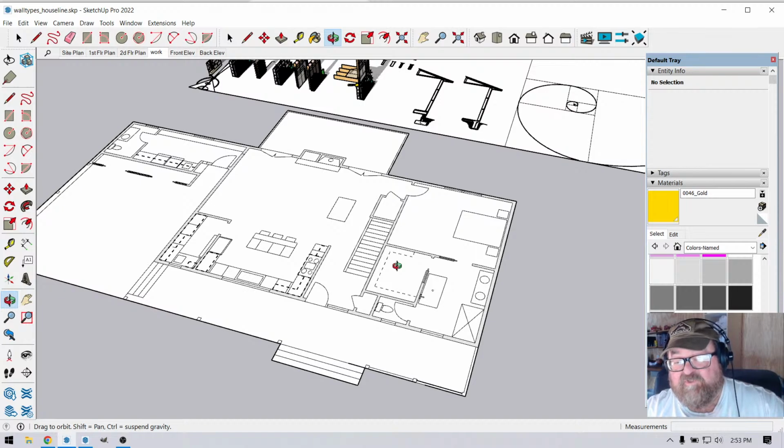Okay, if you misplace your house, let's say you're in an urban environment. I built plenty of homes where we had lots that were 50 foot wide. You had a 15-foot setback on the sides, and the owner said, I want to build a house that'll fit right inside that setback, or maybe it was 10 feet. In an urban environment, you typically will have less of a setback on the sides. So maybe you have 10 feet, so maybe the house is going to be 30 feet.